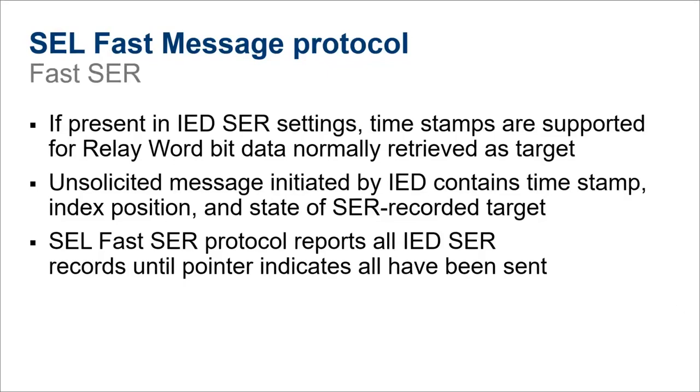If you have unsolicited messages coming from the relay, that will also contain the timestamp and the state of the SER target. And Fast SER protocol will also report any SER records until the relay indicates everything has been sent. So it won't wait for a poll. It will simply push the SER data to the controller.